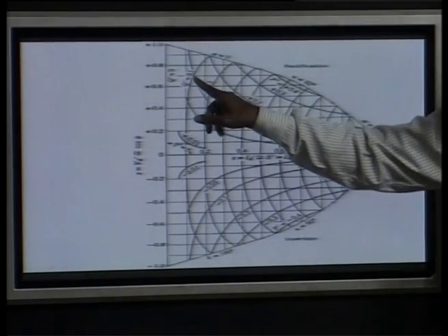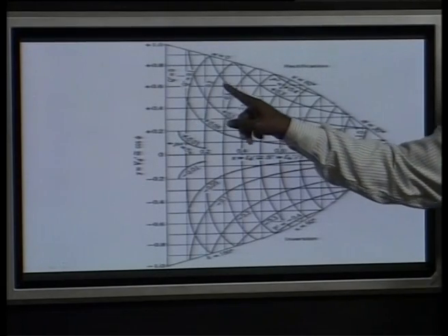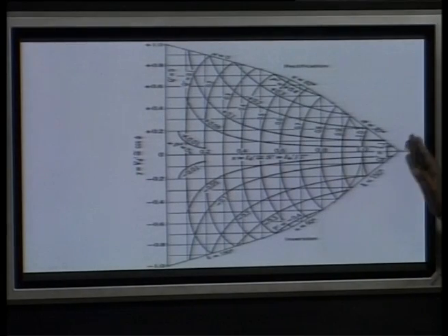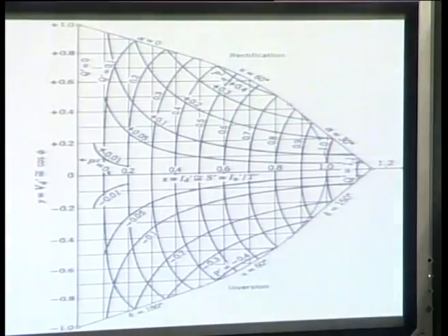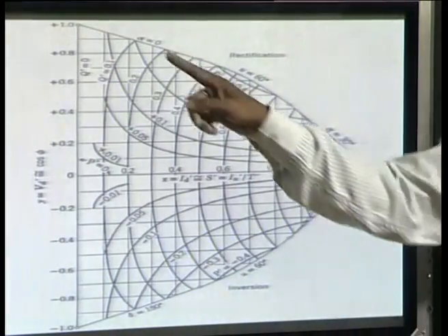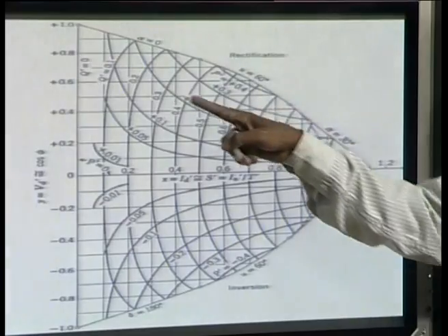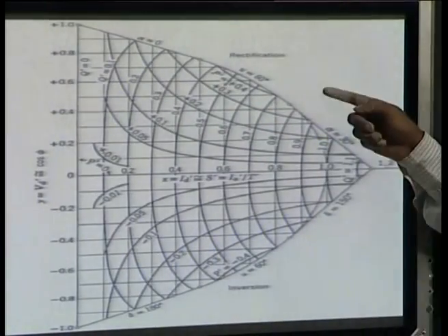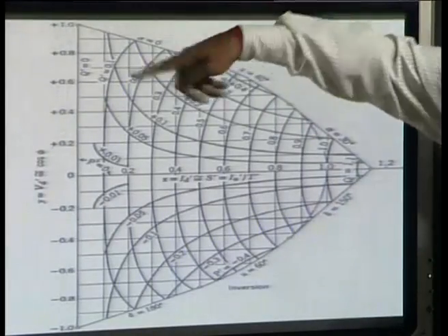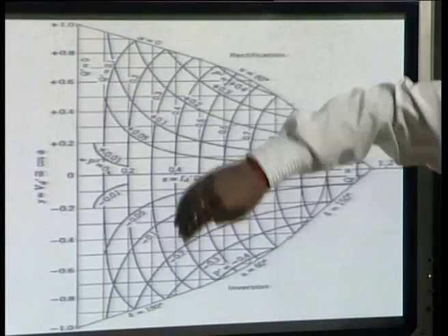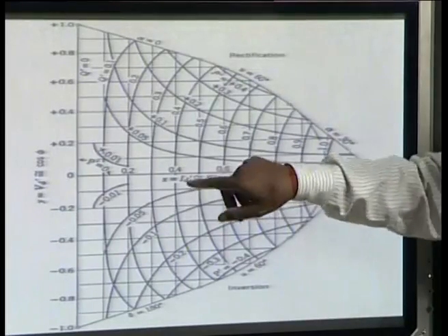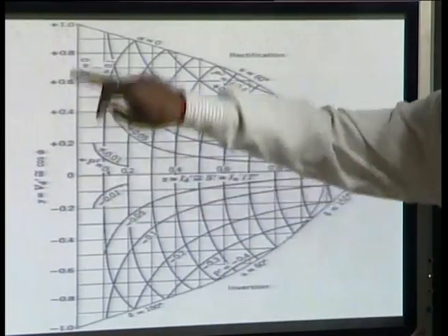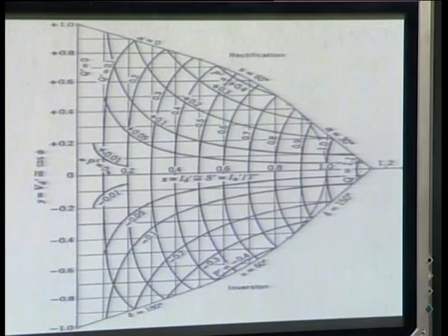So if Q is 0.0 on this axis, then you keep increasing. As I said, if your alpha is increasing, because alpha is changing here, and you are coming to this side, alpha is more and the power factor is worse. So this is the Q, this is your P axis with the P curves, and these vertical lines are your apparent power and the AC side current, and this is your cos phi, that is the displacement factor.